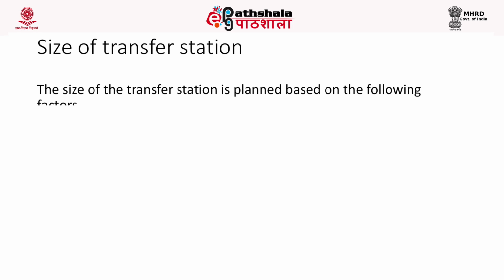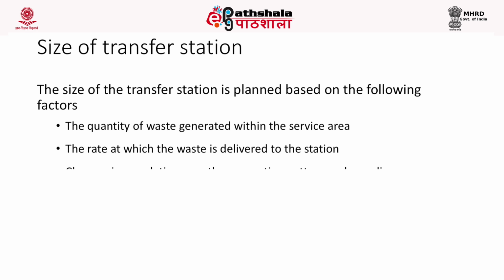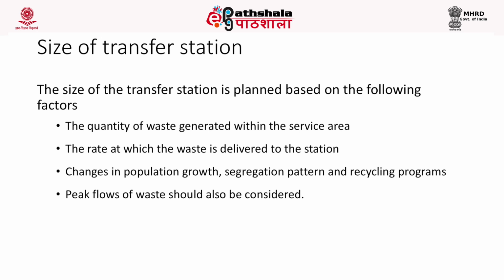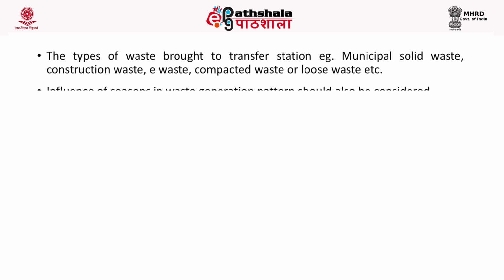Now, let's discuss about the size of the transfer station. The size of the transfer station is planned based on few factors. They include the quantity of waste generated within the service area, the rate at which the waste is to be delivered, changes in the population growth, segregation pattern, recycling programs, the peak flows of waste, and the types of vehicles delivering the waste. The types of waste brought to transfer station, that is the municipal waste or construction waste, e-waste, compacted waste, or any other type of waste.